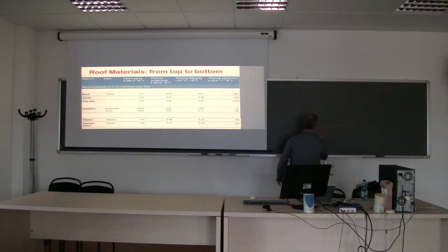So kappa in this nomenclature is equal to K over Cp, right? Yes, I think so, unless I confuse things. Now you have to be very careful with these things, because this is kappa and this is K, and big C tends to be the heat capacity per unit volume. Little c or little Cp in my nomenclature is the heat capacity per unit mass. So be careful, always look at the units. The units will guide you if you're confused about how different books or different papers define things.